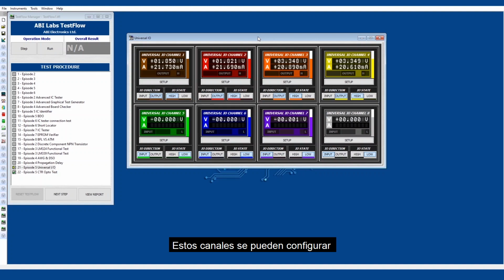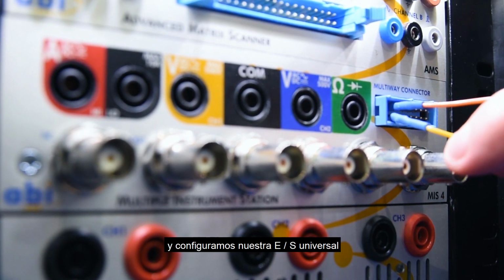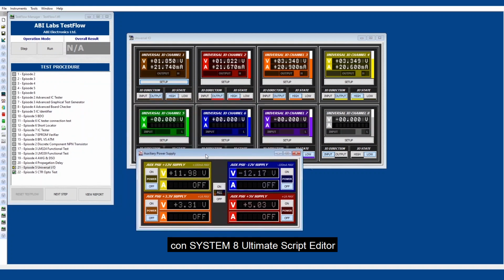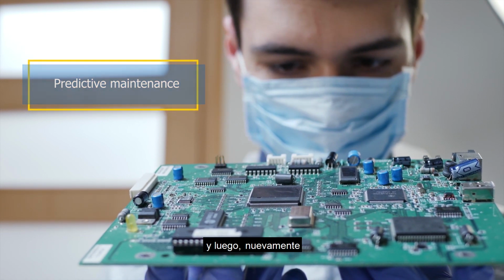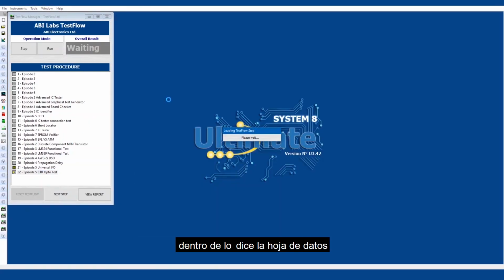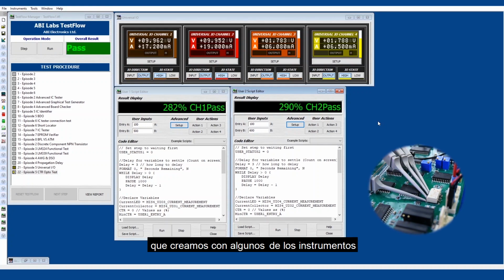These channels can be set to either an input or an output. So we are either driving or we are sensing, and we set up our universal I/O in such a way that we basically created a flow of current, and then we monitored this current with the ultimate script editor. We used these values, did a calculation to produce the CTR, the current transfer ratio, and then again we checked this against the datasheet to make sure that our value lies within what the datasheet says. And again, this is another parametric test that we created with some of the instruments available with the MIS4.